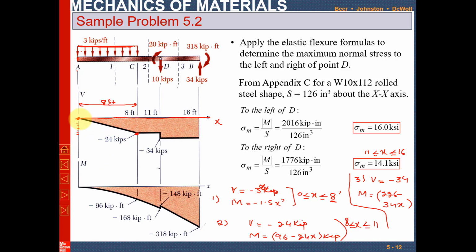So now you can easily join them by joining two points. Or if you are confused, you can take values of x and increase x. You can take x equal to 1, which will give you some point at a distance of 1 foot. Again at 2, it will give you some point, and again at 3. If you join all of them, you will get a straight line. So see, this is the shear force between section A and C.